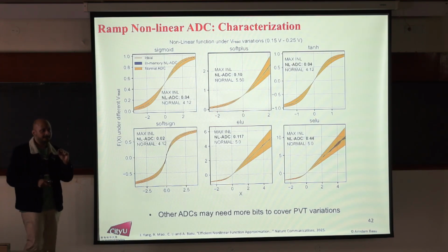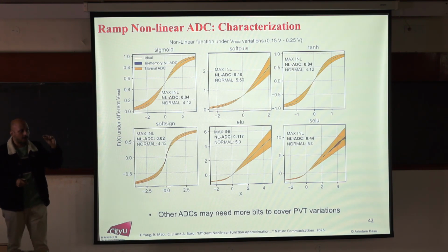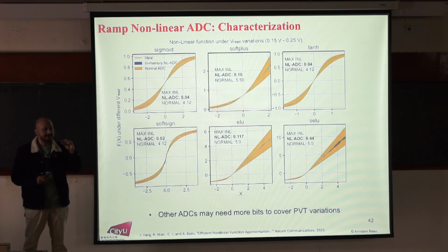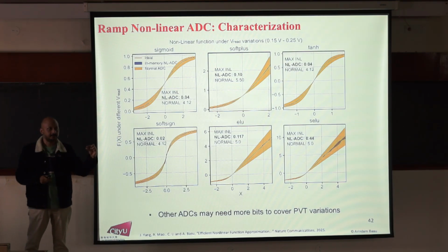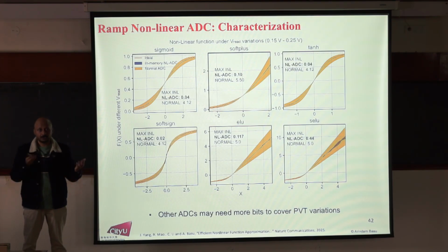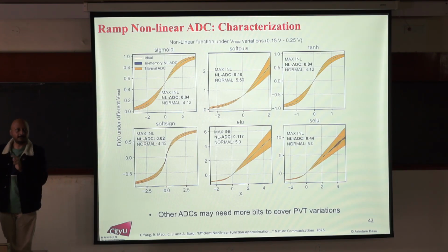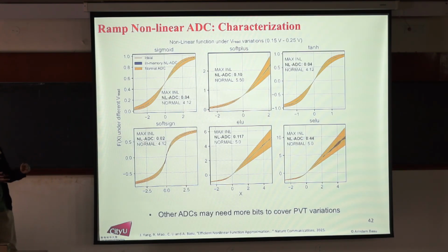What's happening here is our bit cell that is creating these steps is matched with the bit cell that is creating your multiply and accumulate, MAC. Because of this inherent matching, to a first order, we get cancellation of any non-idealities. This is called replica biasing in analog circuits, and that's what helps us cover these PVT variations very nicely.